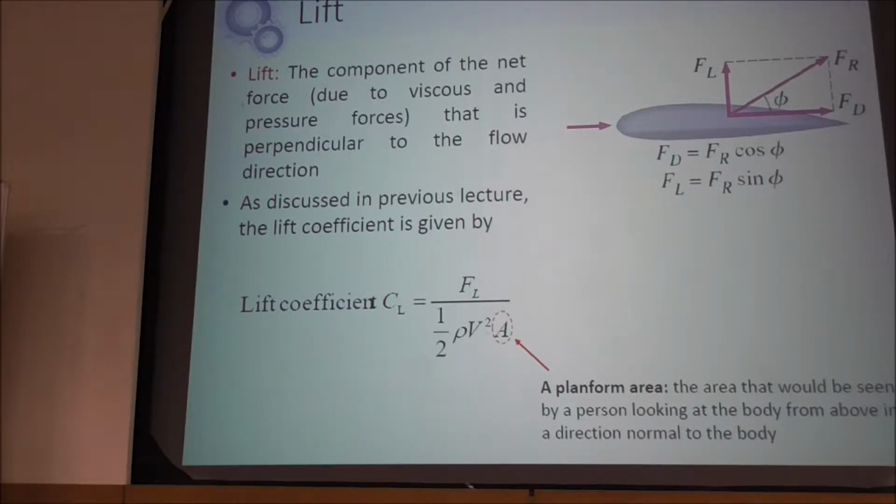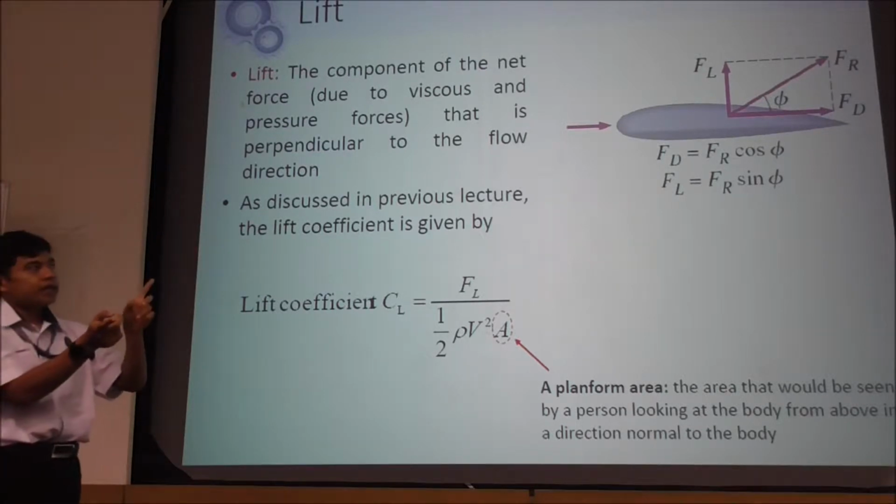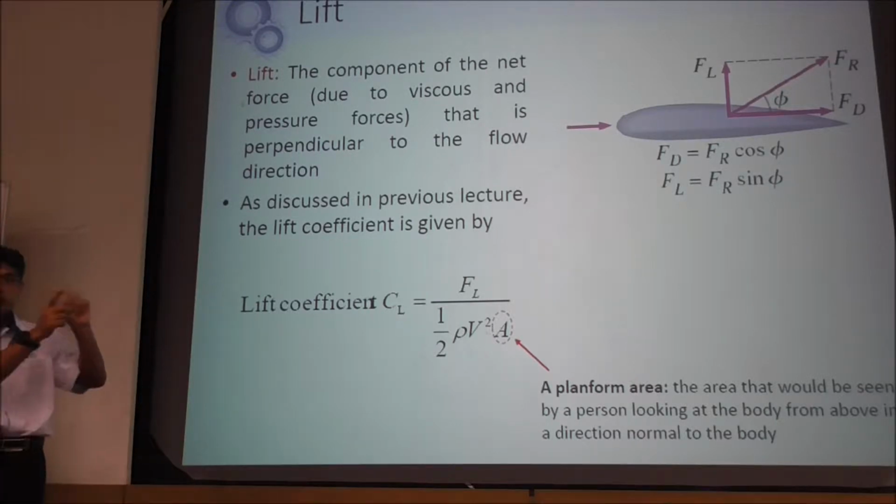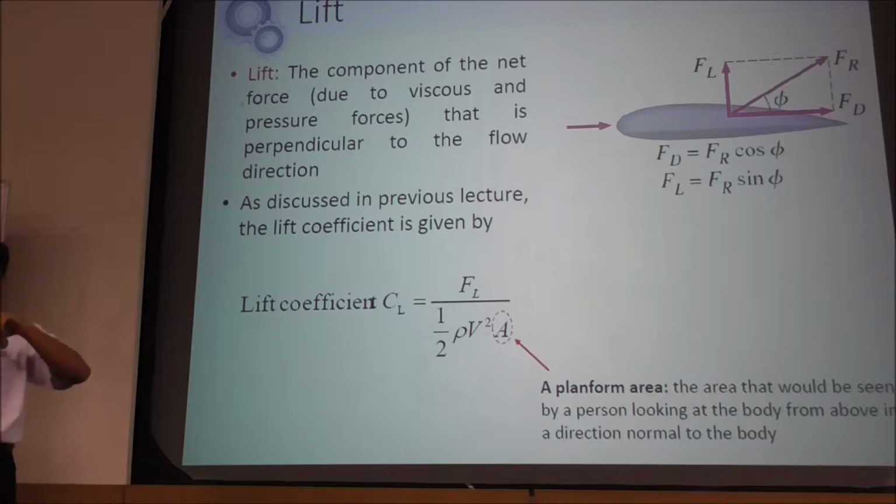So from one force you divide it into two, tangential and normal, and each contributes to lift and drag. At the end, from that single force you have four force components, and those four join to become either the lift or the drag component. So it is 1 into 2, 2 into 4, 4 into 2.